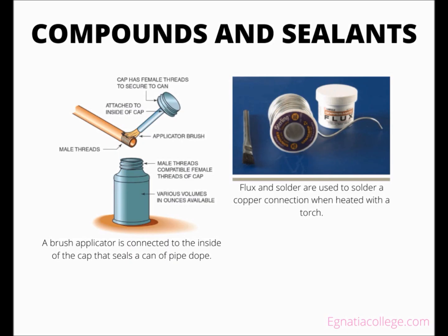Soft copper tubing can be connected to another copper tube or to a piece of equipment with a flared connection. A flaring tool is used to fold or spread copper tubing to mate with a compatible manufactured flared fitting. The fitting design and flaring tool have compatible flare angles to ensure that a proper flare is created.